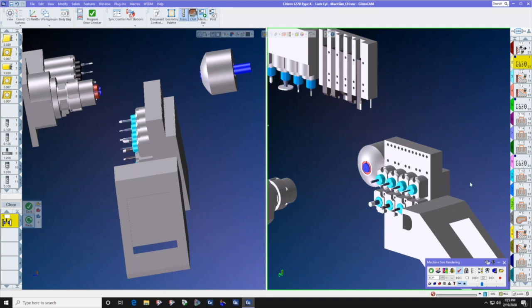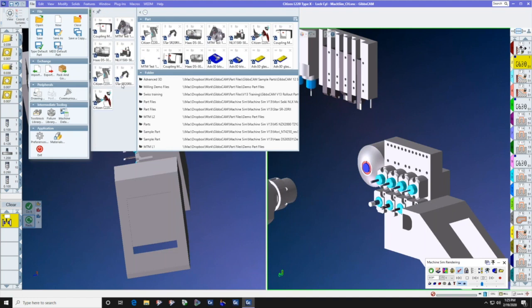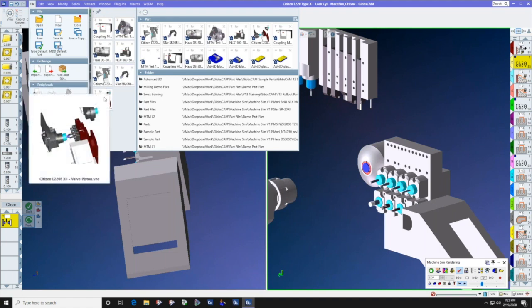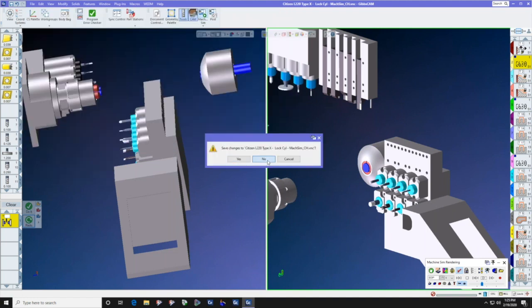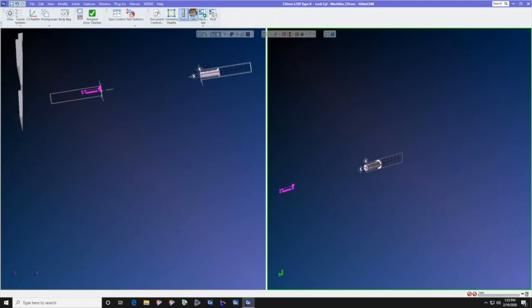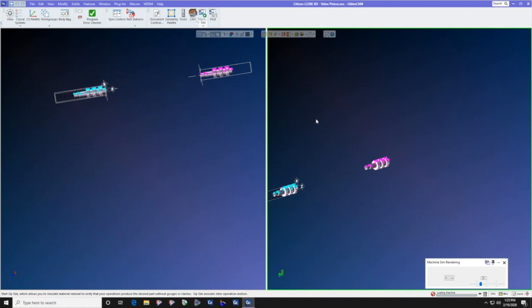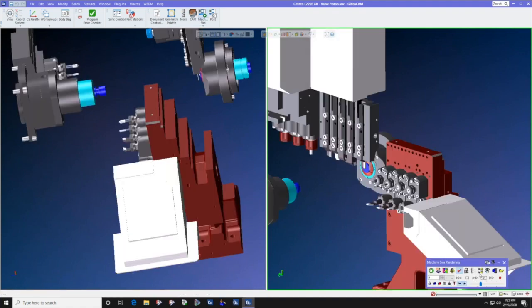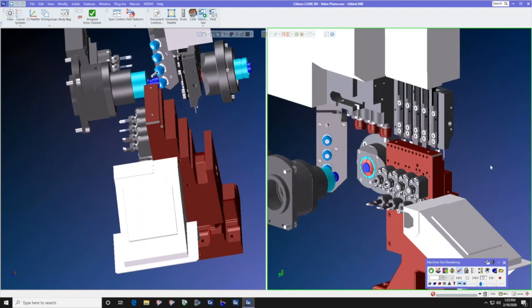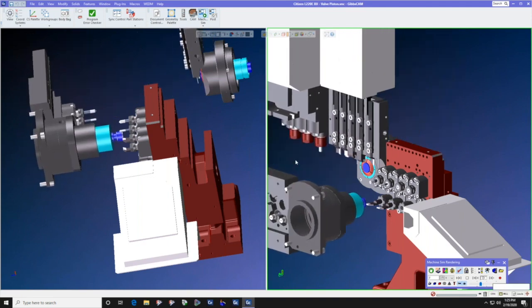The Swiss machines also come in many different flavors. There are Swiss chuckers, and Swiss machines are now approaching another stage in which they have decided to go back to turrets on certain types of machines. The ECAS machines had a turret, and now Tsugami machines have a third generation of Tsugami machines that have a turret on it, where this is a gang style machine with a B axis.